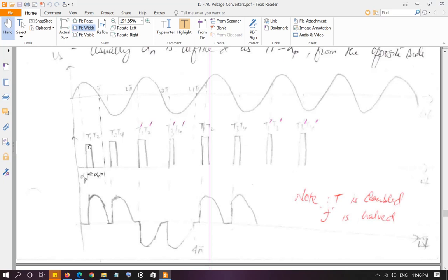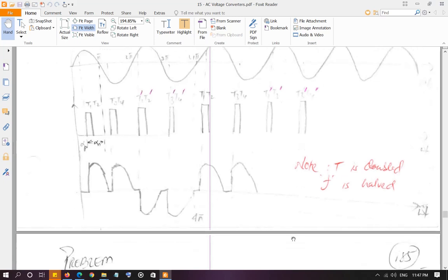So the important thing is that you understand the sequence in which thyristors are going to be fired to produce a specific output for a specific frequency. Okay, it is important. I will advise you to do some exercise. I'm not assigning any homework, but do some exercise. Let's assume that you want the output frequency to be 1/3 of the input, so if it is 60 Hertz, you want the output frequency to be 20 Hertz, and see how it's going to work out at the output, right? See which will be fired and how the output is going to look like.